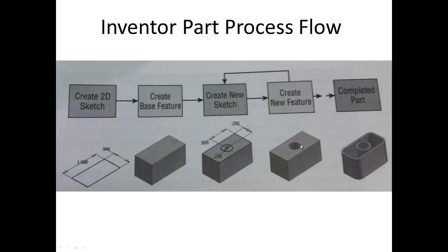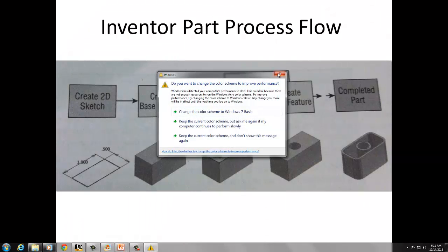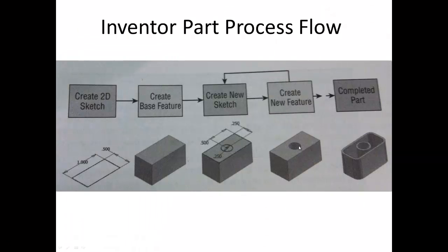Here we just extruded downward with a circular 2D sketch, so we get a hole. And then after a few more steps, we've managed to extrude in through everywhere except that hole and the periphery of the part. I think that was done using the shell command.